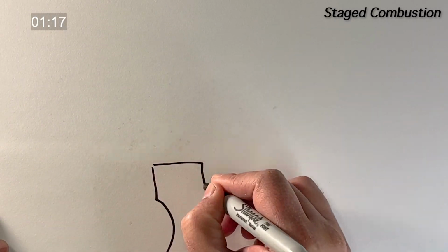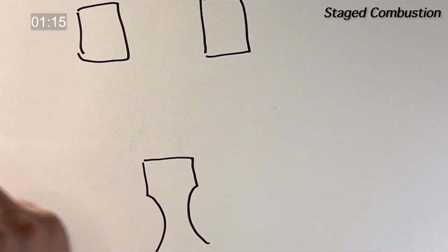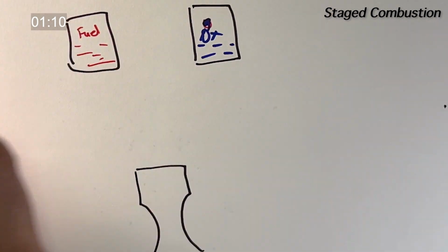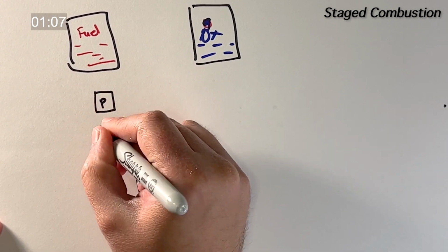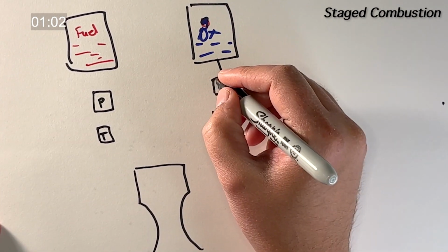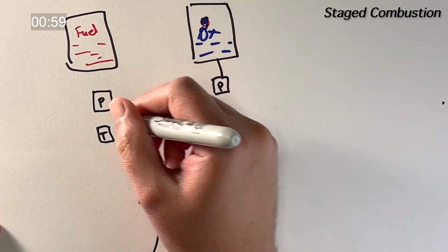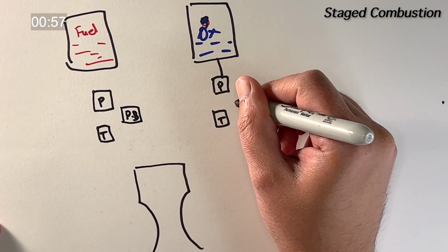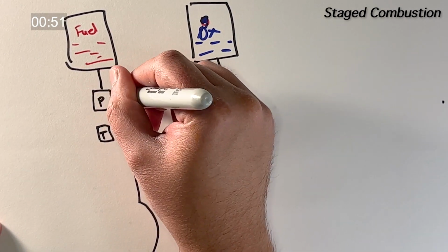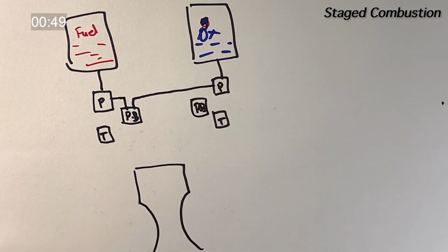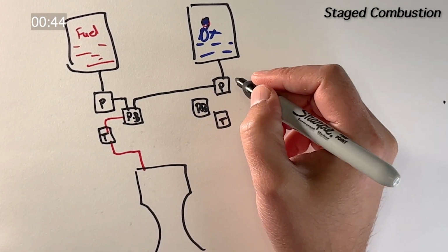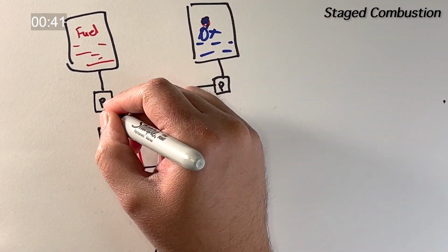Another type of closed cycle rocket engine is the staged combustion cycle. While an expander cycle type engine does not feature a gas generator, a staged combustion cycle engine consists of a pre-burner or a high pressure gas generator that burns all of the fuel with a part of the oxidizer in the case of a fuel-rich combustion cycle, or all of the oxidizer with a part of the fuel for the ox-rich staged combustion cycle. The exhaust is then used to drive a turbine to spin the pumps, but post-turbine, the exhaust products, which contain all of one propellant and a part of the other, are plumbed into the main engine chamber via the injector. Here, mixture A meets with the remainder of the other propellant to complete the combustion process.